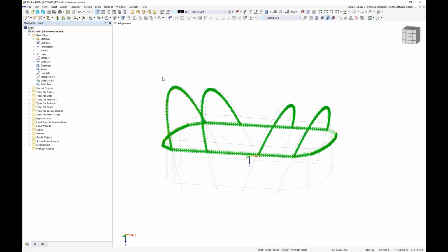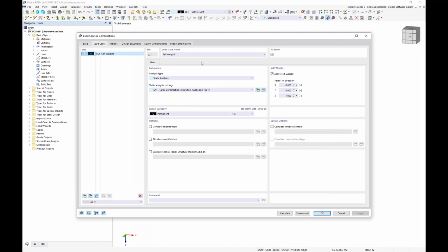held from the surface. And for this, we need a load case. Here, I open a new, or I modify an existing load case. In this case, the first one, we define here pre-stress with the action category pre-stress. The name here is irrelevant. The only important fact is this yellow flag here, because this flag gives the program the task to make a form finding process.